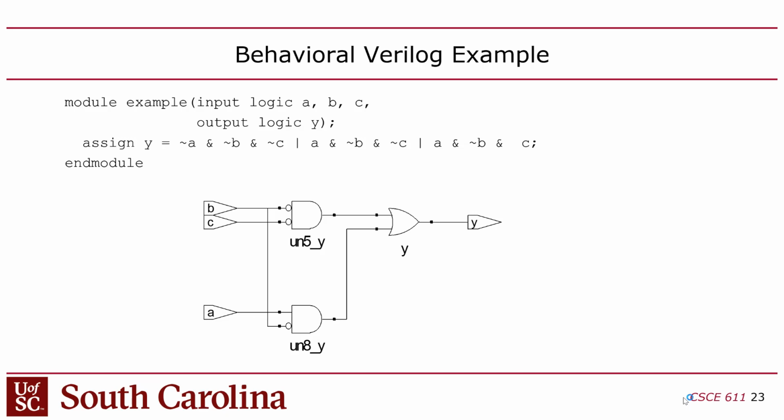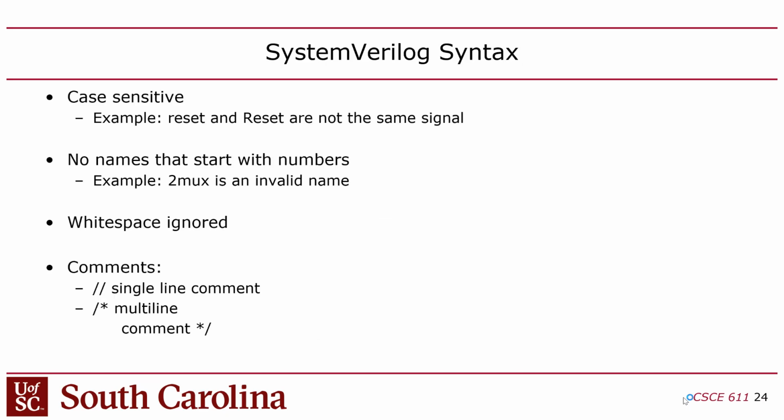It'll show you the gate level description. Now this is obviously before it puts it on the FPGA. It's just saying, well, I can make that circuit with that netlist or that schematic. And then when you put it on the FPGA, it has to map each one of these gates to a spot on the FPGA, which is, again, what you did in 211 when you decided which gate to allocate on the 7400 series chips. Of course, you do that by hand, and this process I'm describing is automatic.